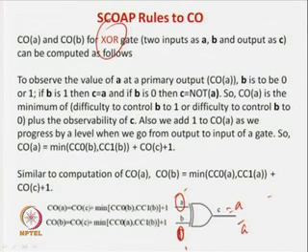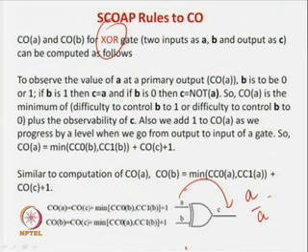Now, both of them serve our purpose, because our goal is that we have to observe A, we can propagate it here. So, we can observe A also, we can observe A prime also, both of them solve our purpose. Like this may be normal case 0, fault case 1, and this may lead to normal case 1 and fault case 0. And both of them will lead to our fault detection. So, propagation of A or A prime, both of them suffice our purpose.